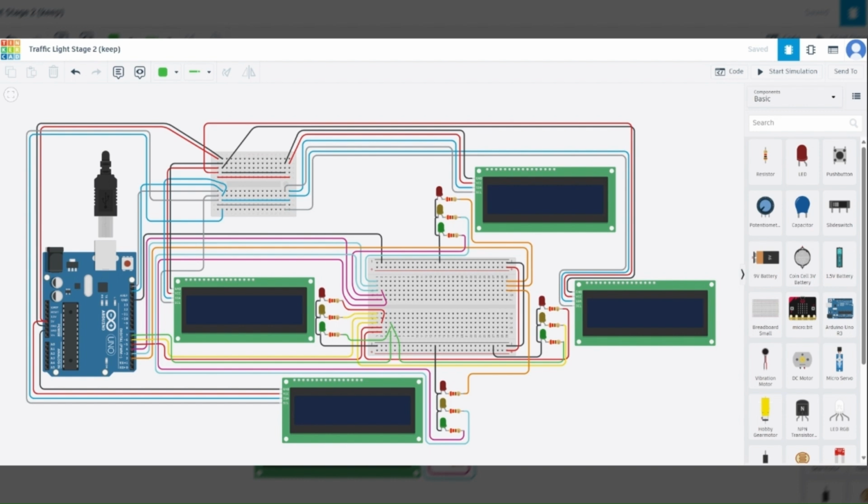The traffic light logic is managed using a switch case structure. The switch statement evaluates the current phase, and each case responds to a specific traffic light configuration. This makes the code modular and easy to expand or modify. The don't walk message now appears when the opposite direction turns yellow, adding a realistic buffer before the green phase.